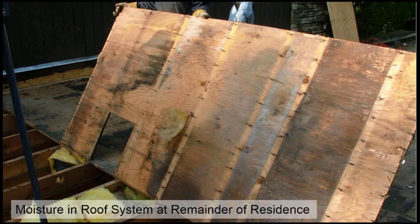We later went through the rest of the house. Actually, what happened was the hygienist involved decided to take some readings on some of the incandescent cans across the rest of the house. When he did that, he found very high mold spore counts throughout the attics of the whole house. Although it wasn't as bad and dripping on the inside as it was in the natatorium, the problem still exists. In fact, we've been on many problems where this exists that were far less humid than you would have in a natatorium and have the same problem occurring.